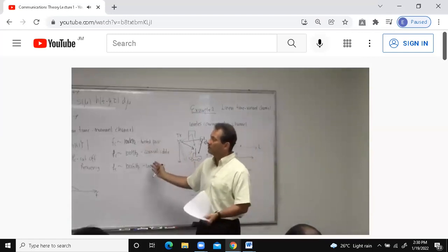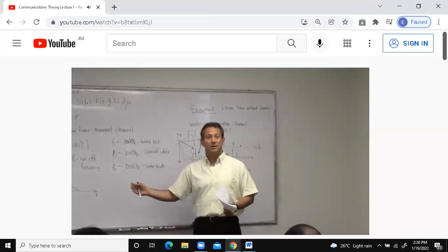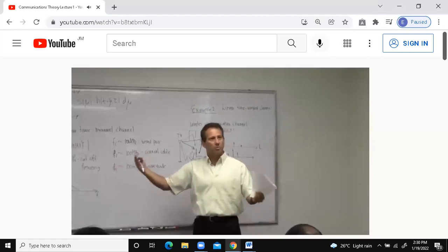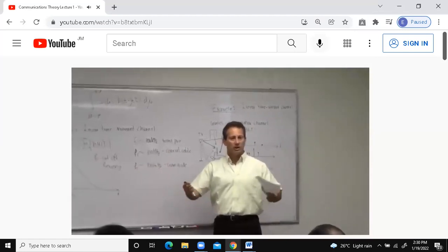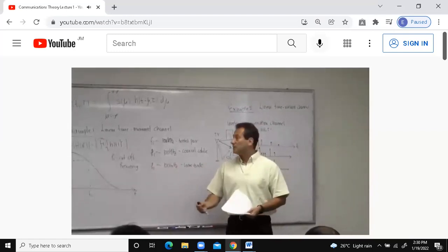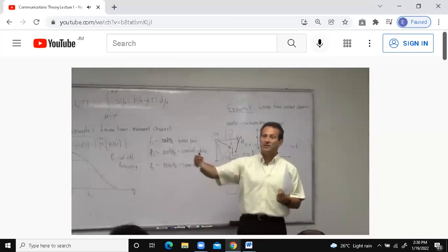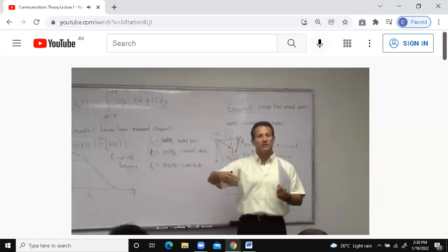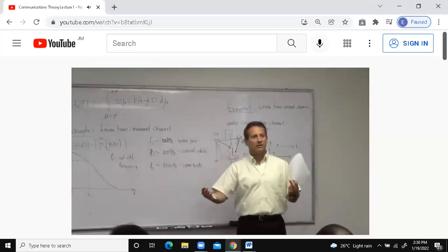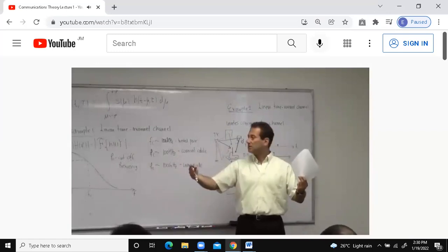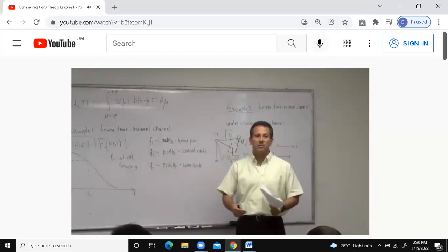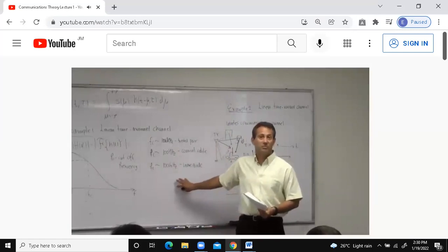But all the channels that we have covered are so-called linear channels. A channel is linear, it's described through linear system theory, right? If superposition holds, convolution holds, I put two signals at the input, I expect to see two signals at the output, they're not mixing together. The majority of channels, due to the nonlinear devices that you have along the way, like power amplifiers and mixers, would actually introduce some sort of nonlinearity. And what happens is the signal now gets additional distortion, where there's a mixing in the spectral component. We're not going to talk about it in this course, just be aware.